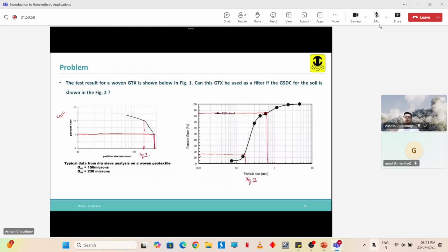Then you take one more size, 230 microns, a larger bead size. Now 100 grams of 230 micron beads you sieve. There you will see that 95 grams is retained and only 5% of the 230 micron is passing.